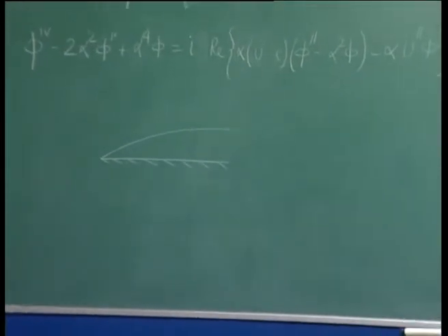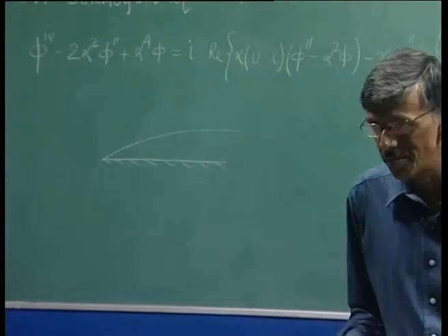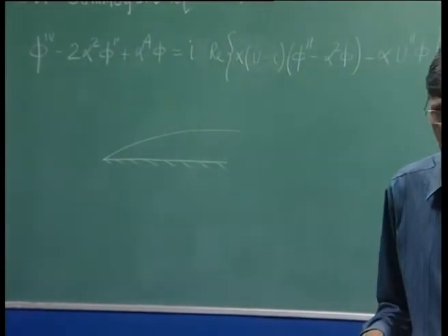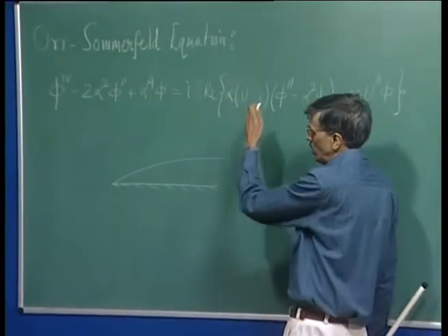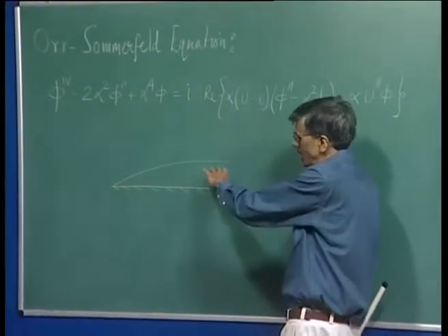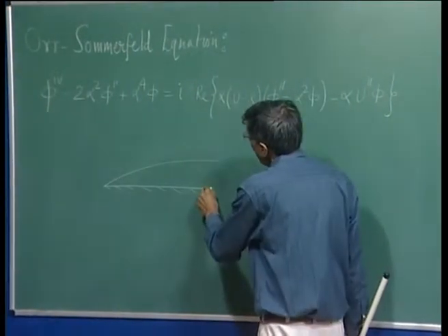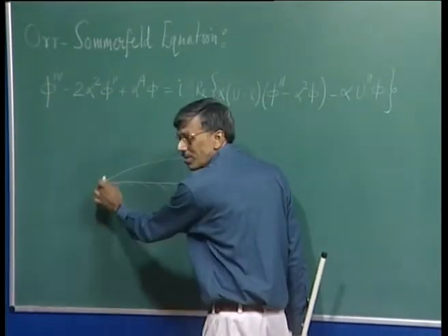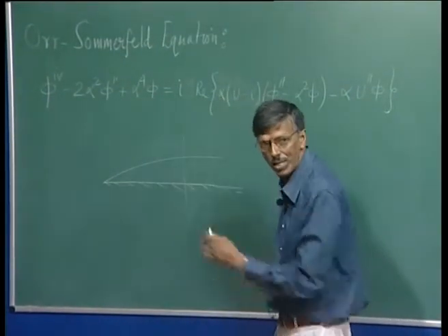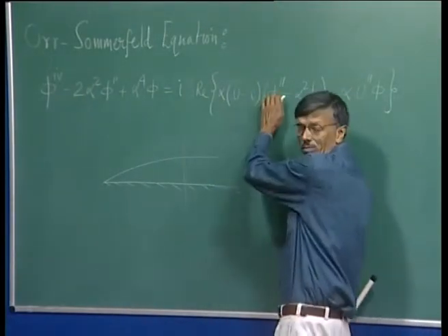We got this because we made some vital assumptions. What was the prime assumption? That the flow is parallel. That means we are going to talk about that part of the flow where the boundary layer does not grow anymore. So, we would exclude this part of the flow where you can see a significant growth of the boundary layer. That part is not considered, but in this part this works.